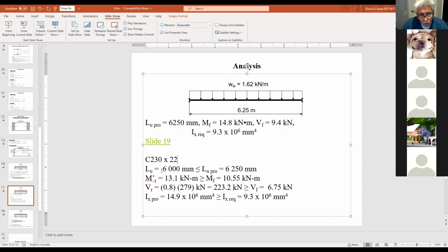And of course, here we're telling everybody the LU that we picked is smaller than the LU provided. So therefore we got to be careful. Here I'm going to put my MR value of 16. I'm not worried because if I do a calculation, I know that when I go up to 6.25, I'll still be higher than 14.8. So therefore, I'm giving myself sufficient.